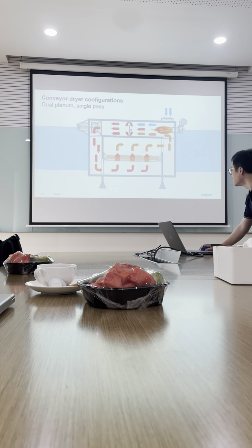Before the plate, the cold air and the heated air are not mixed. That is not good for the recirculation fan, so we need to mix them together and provide uniform temperature air. In the end, the recirculation fans push air into the heating zone.